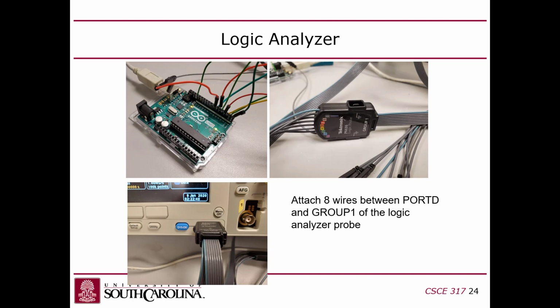There's a probe, you plug it in the logic analyzer, and it splits off into two 8-bit buses. So there's 16 bits in total. But each one of these little black boxes that split off has eight wires. And I just plugged each one of those into each of the 8 ports of port D.